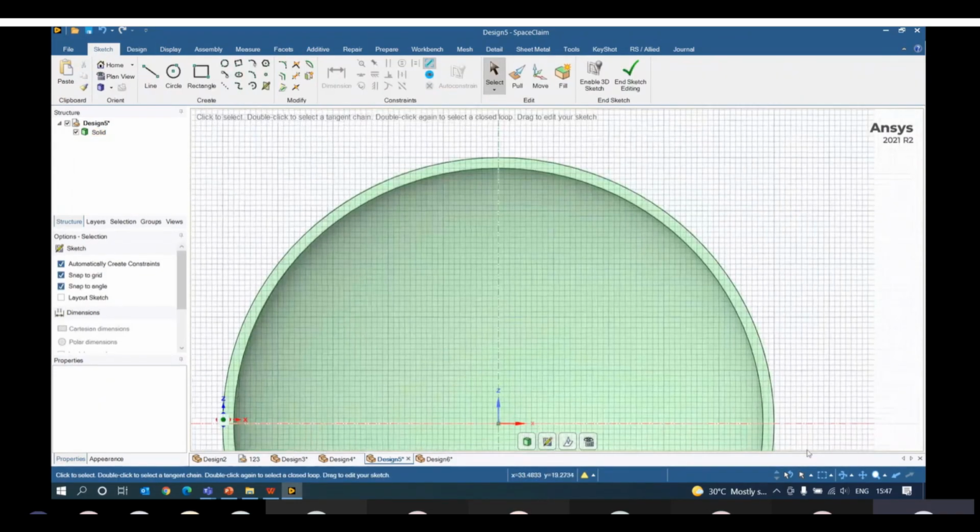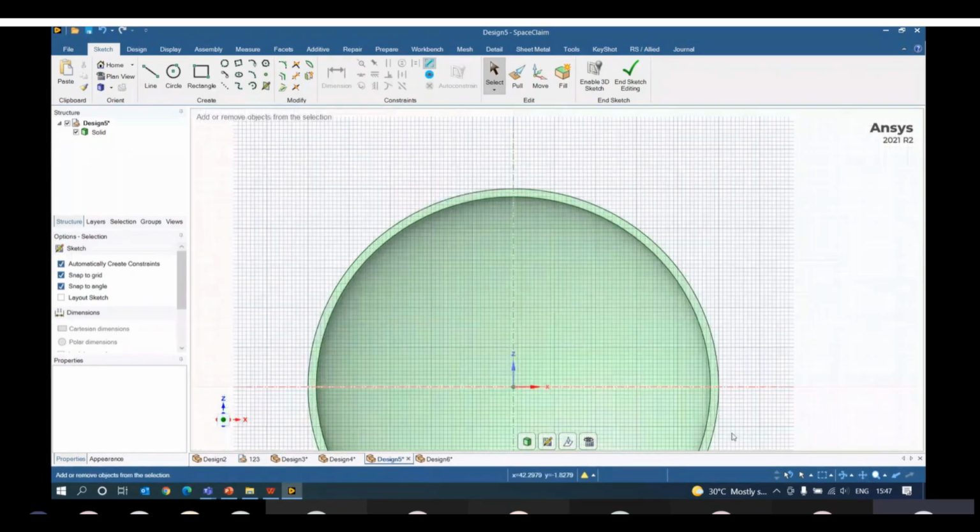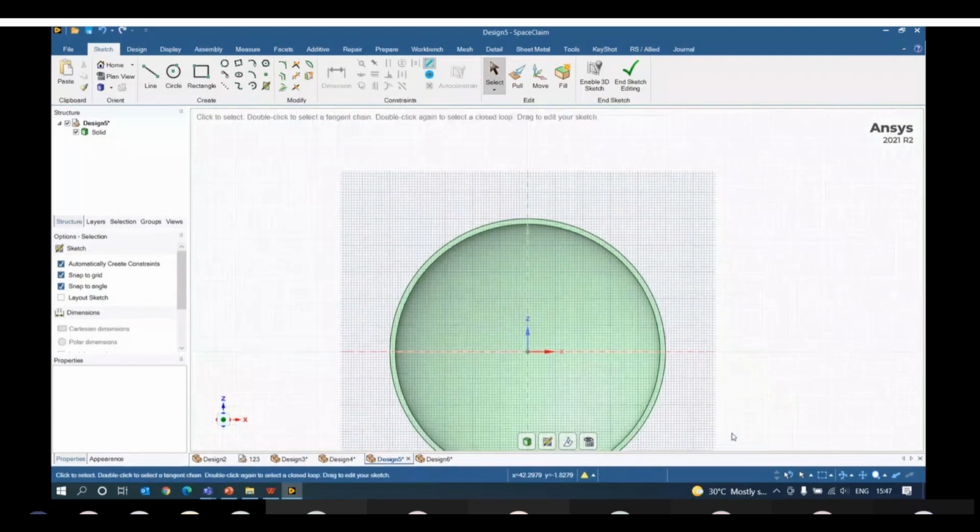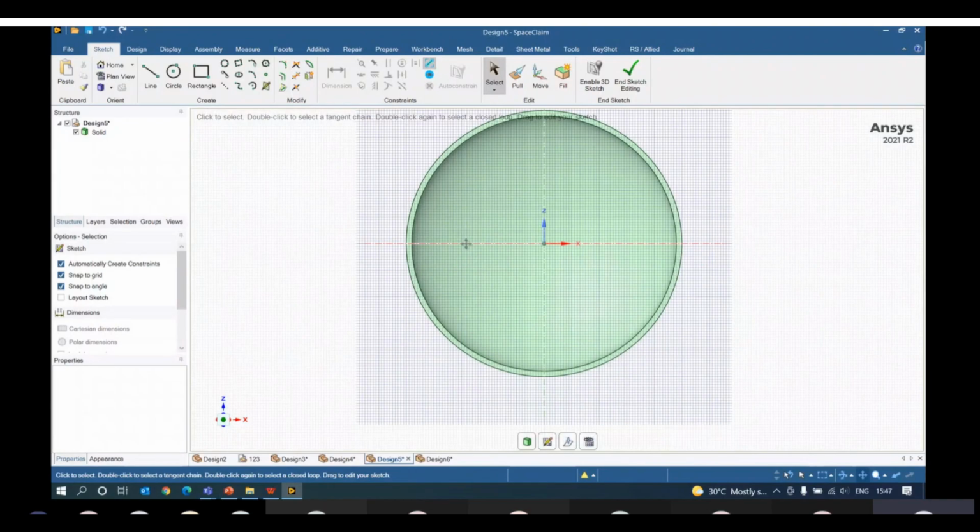And here you also have options, like to zoom from here, it's always difficult to keep zooming all the time, rather you can go for Control minus and Control plus. Okay, and if you want to pan your geometry, make use of the pan tool from here.